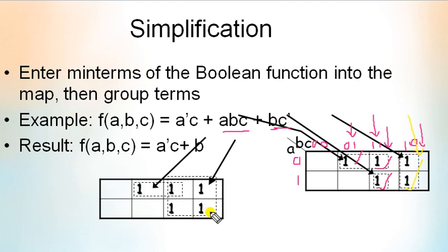And next step, we'll write the result using this Kmap after grouping. So first of all, group 2 ones and group 4 ones. For this group, the value of A is 0 and BC values are 0, 1 and 1, 1.